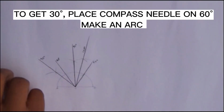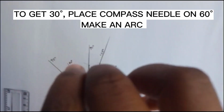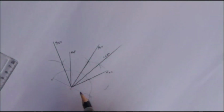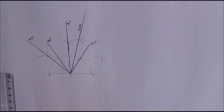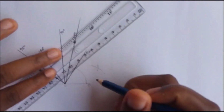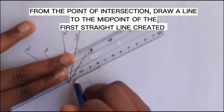So to get 30 degrees, you put your compass needle on 60 and you make an arc, and then you come to point B and make another arc. The point of intersection between these two points, 60 degrees and this point B, is your 30 degrees.